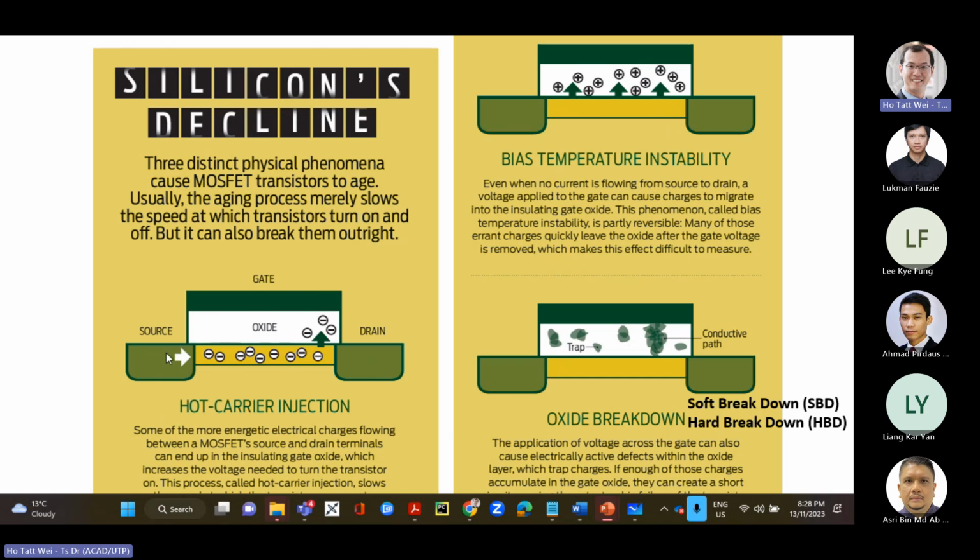Hot carrier injection comes from the fact that there's a current here, and you're actually pulling two ways, this way and this way. So you're slamming very quickly the electrons or the charges, the holes, into this, right? It tends to be more here, right? Because it starts to accelerate here, then it's very fast here, then boom, it goes there. And here also is where there's a pinch off. Less charges here, so it's very dense carriers here.